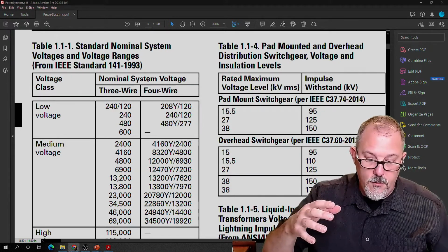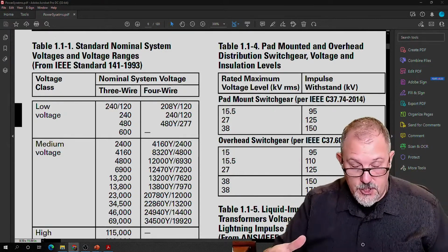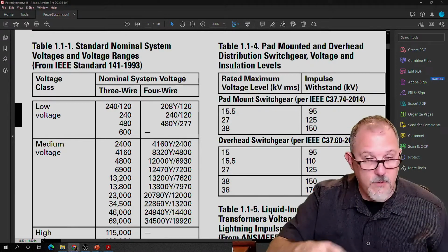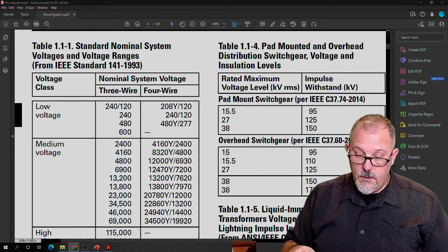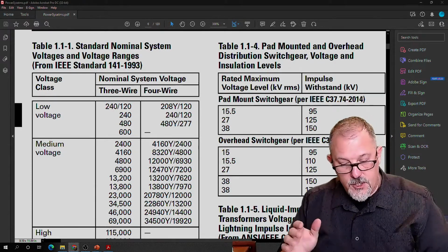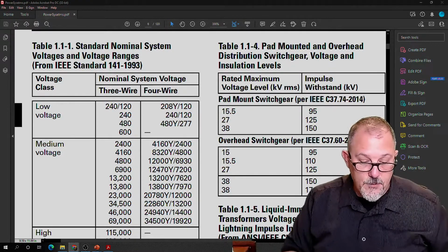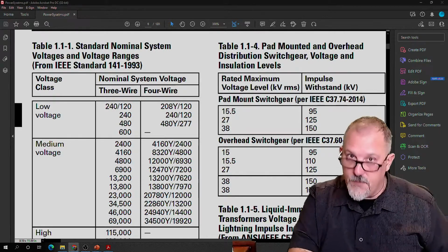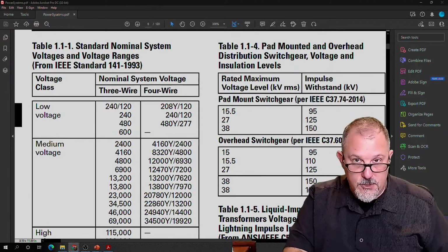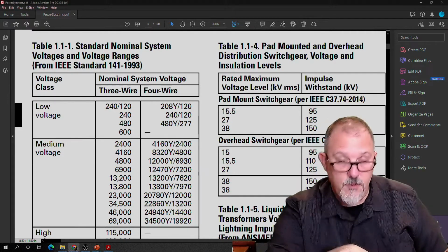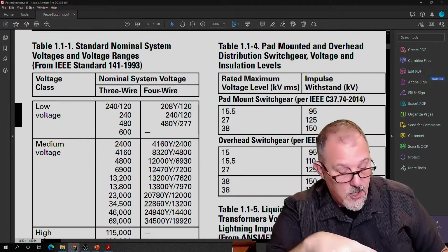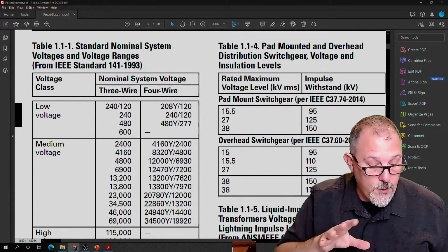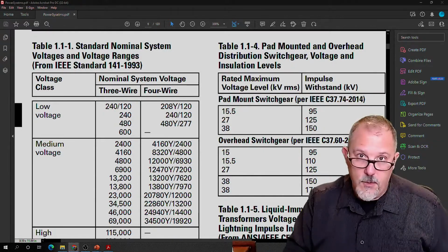So lower voltages or higher voltages will impact how your designated loads perform. And there are some good tables. For example, table 23 in this gray book, the edition that I'm referencing right now, says general effect of voltage variations on induction motor characteristics. Now, remember, this is not variable frequency drive solutions. These are across-the-line types of motors. But regardless of where you're at, there are motors in a lot of equipment.